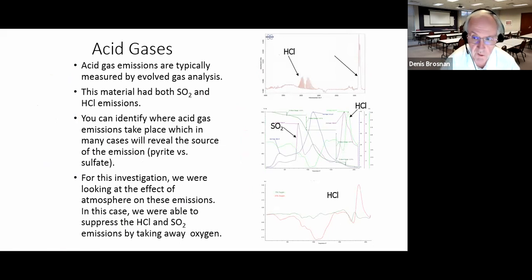In the last class, you'll find that the chlorine in heavy clay products is usually associated with the organic phase of the bricks. So chlorine, unlike fluorine, chlorine is not in substitution within the clay crystal structure. It's present in the organic matter that's there. There could be salt sources in the area where the clay was extracted, like sea spray, I don't know. But nevertheless, we're going to get chlorine emissions, sulfur primarily from the pyrite, but can be present from the fuel in the body.